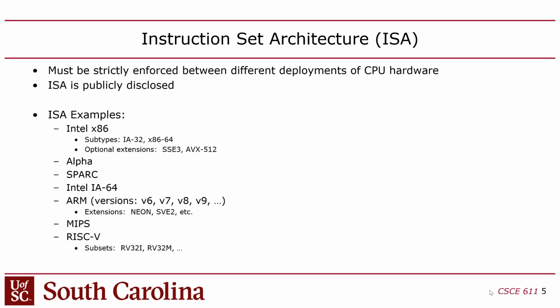You might remember from 212, in MIPS there were R-type instructions, which were register instructions, and I-type instructions, which were immediate instructions, right? For whatever reason, the destination register field was different in both. Why? There was no reason for that. It required you to add extra hardware to deal with it. It was dumb. RISC-V fixes that. So it eliminates some of the miscellaneous muxes and control logic that you had to put in to fix the dumb decisions they made in MIPS.